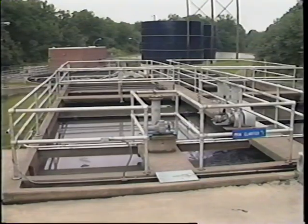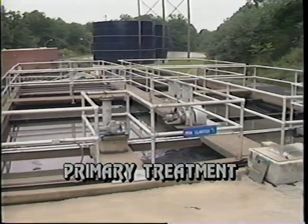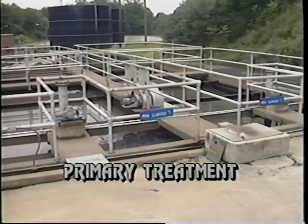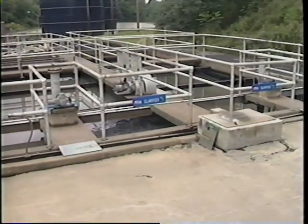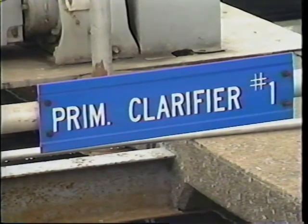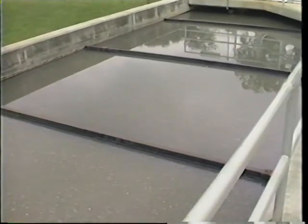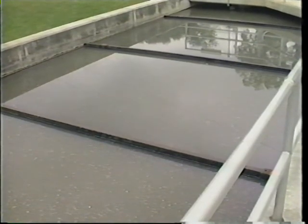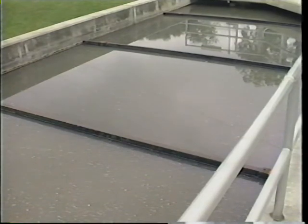Now that the wastewater has been properly pre-treated and its volume measured, it goes to a process called primary treatment. The wastewater is now routed into and through a large tank or basin called a primary clarifier. The flow velocity in the primary clarifier is reduced to a fraction of a foot per second, causing the settleable solids to fall to the bottom and the floatable solids to accumulate on the surface, resulting in clarified wastewater.